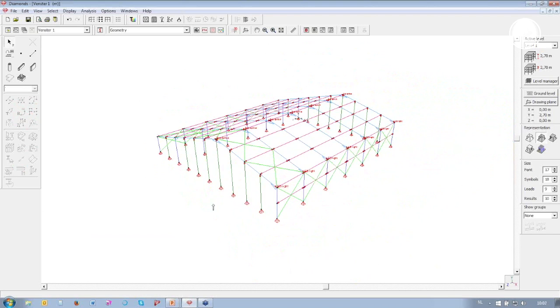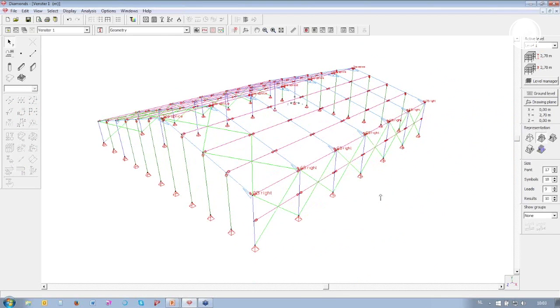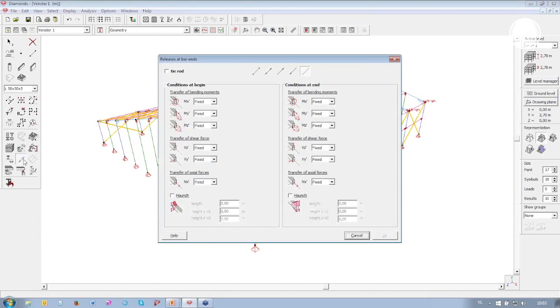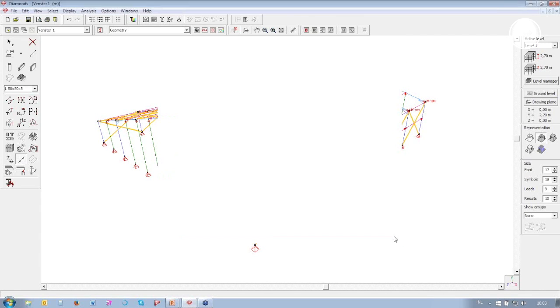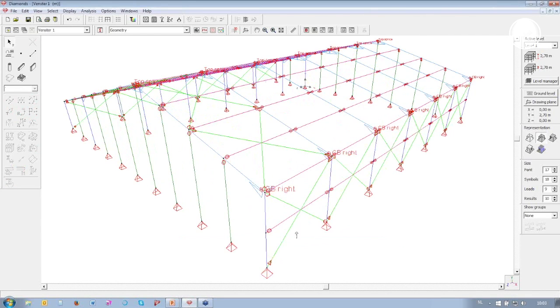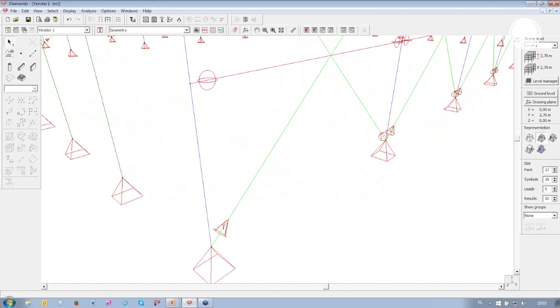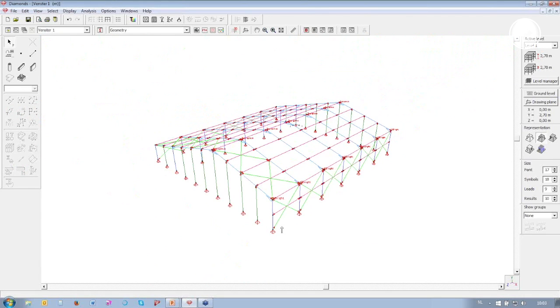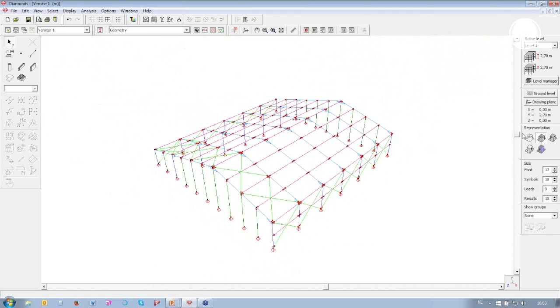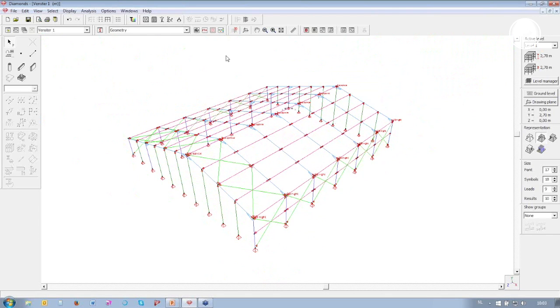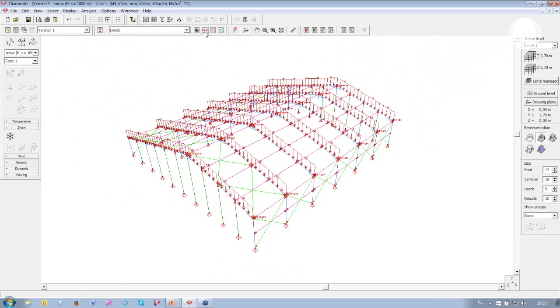Okay, I think we're about done. Just one more thing for the wind braces. The wind braces usually are capable of only taking on tension, so we can define this one or set this one as a tie rod. And tie rods are represented by the little triangles in the software. So going to the load.